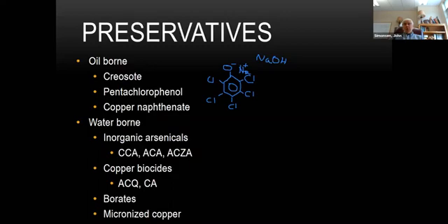CCA works great. It's one of the best preservatives people have found, except that it is toxic to non-target organisms. But it's cheap and it's effective. There are CCA poles that have been in the ground for more than 50 years and they're doing just fine. So you just have to get the retention right.